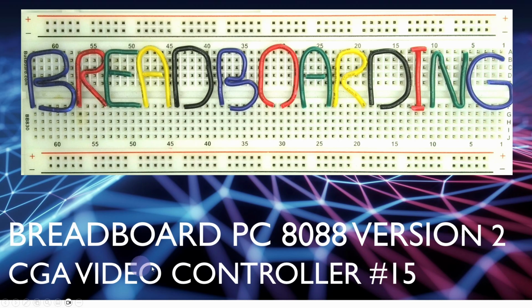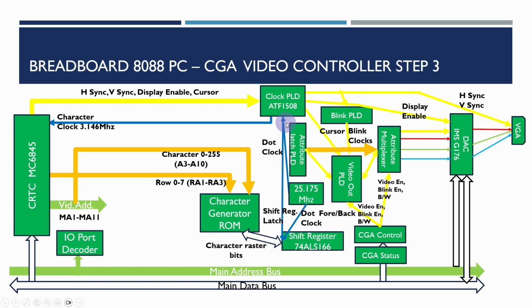This is video 15 of the Breadboard PC 8088 version 2 series. And in the previous video what we got was a lot of this logic here that was previously in separate PLDs, all working in the one PLD with our CGA control and CGA status registers. We've also added the CGA color register, although until we use the graphics modes we're not really going to be able to test that.